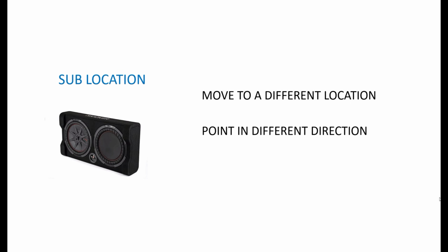So particularly in hatchbacks or SUVs where the cargo space is the same area as the car cabin, it's often the best position to fire it back towards the tailgate, right? Because you get boundary loading, right? In a sedan where the trunk is actually enclosed, it varies because you have what they call coupling. So the trunk is kind of decoupled from the cabin, and therefore the rear seats and things will block or filter out certain frequencies.